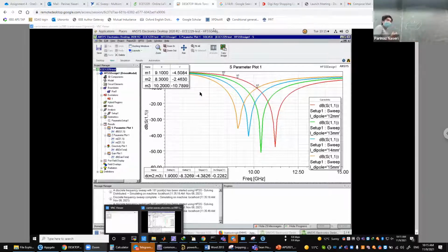Okay. So it's a rectangular patch, and you will study it, but when you excite it, it is at a certain way. For example, if this is the length of the patch, we're looking at this cross section like here, right? The current has to be zero at the edges, right? Because the metallization ends, the current ends. Now, if you look at the voltage, though, the voltage looks like this. Just because when the current is maximum, the voltage is minimum, and something like that.